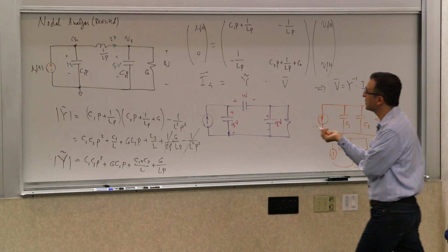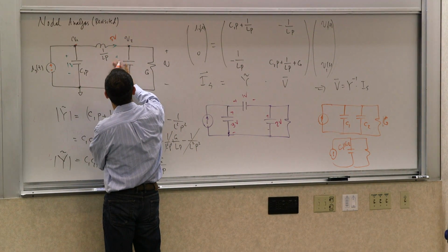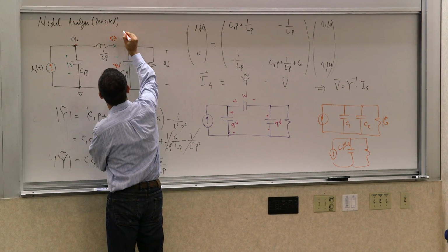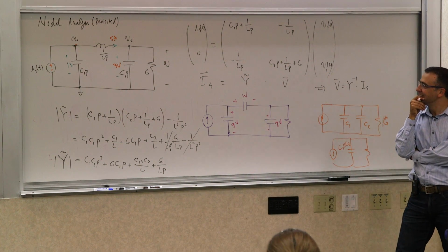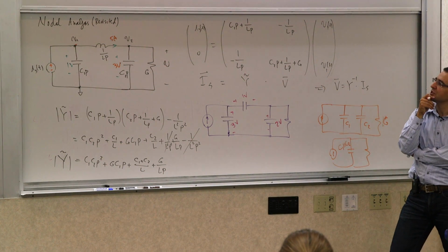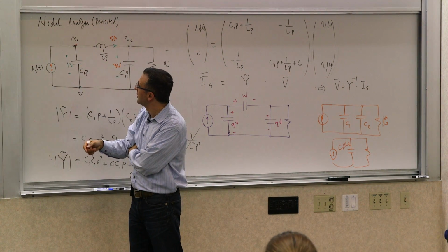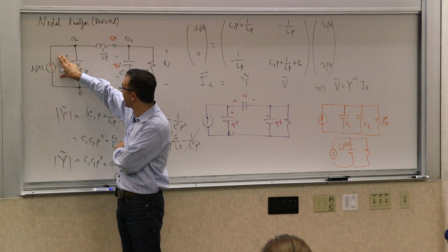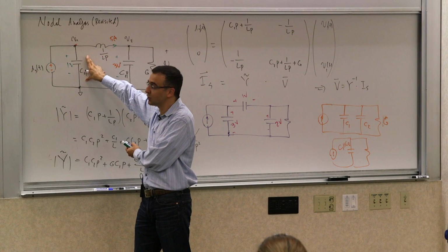The current of the inductor can be whatever it wants, right? It can be 5 amps and 3 volts. But how about the voltage across that capacitor? Can I set it independently, whatever I want? No. If this became a voltage source, then that voltage source will tell me what this voltage is. I can't set it arbitrarily. So I don't have that degree of freedom.